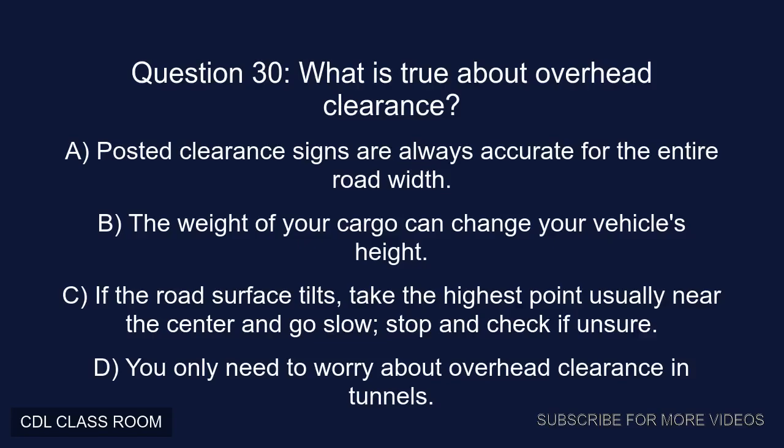Question 30. What is true about overhead clearance? A. Posted clearance signs are always accurate for the entire road width. B. The weight of your cargo can change your vehicle's height. C. If the road surface tilts, take the highest point usually near the center and go slow, stop and check if unsure. D. You only need to worry about overhead clearance in tunnels. Correct answer, C. If the road surface tilts, take the highest point usually near the center and go slow, stop and check if unsure.